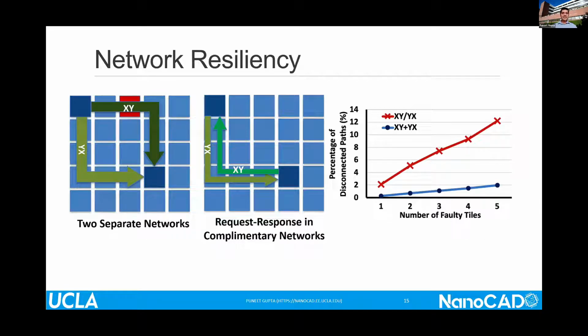The last bit is a little bit about fault tolerance. There's a lot more on fault tolerance that was in the chip, but I want to highlight just one aspect, which is that a big part of our fault tolerance comes from a fault tolerant network in this design. Our primary approach is we have 1,000 of these tiles available, which are essentially doing the same thing. So the easiest and most flexible fault tolerance we could think of is that if a small number of them fail, we want to be able to bypass them and let the rest of it work.